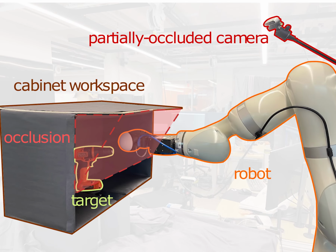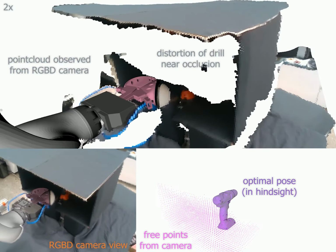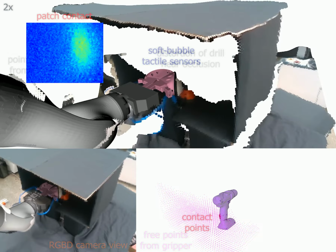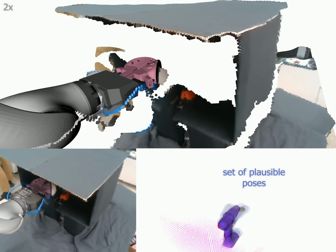Now, we show our real robot probing experiment, where we estimate the pose of a partially occupied object in a cabinet through probing it. Note that this view is not available to the robot. Free points come from both the camera and the swept volume of the robot, while known SDF value points are collected from contact. Note that the camera is unreliable near occluding edges, and so we only use it to provide free space. In other situations, when combined with segmentation, it can also be used to provide known surface points.